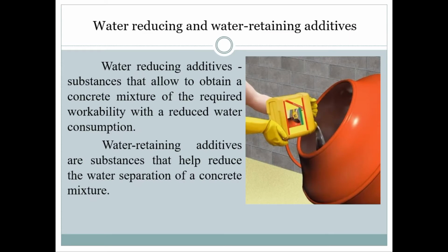Water reducing and water retaining additives. Water reducing additives are substances that allow obtaining a concrete mixture of the required workability with a reduced water consumption. Water retaining additives are substances that help reduce the water separation of the concrete mixture.